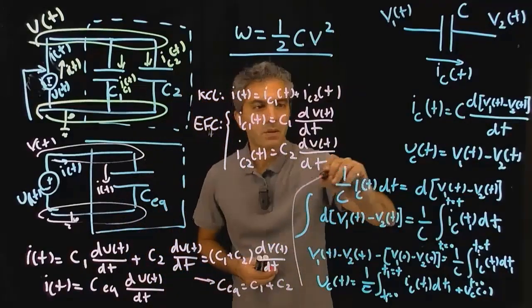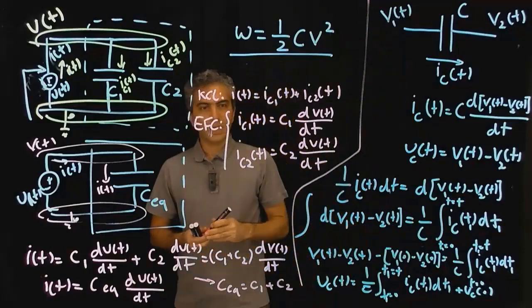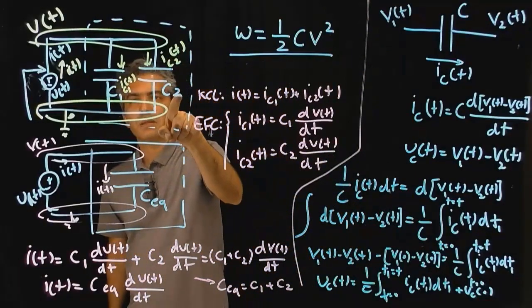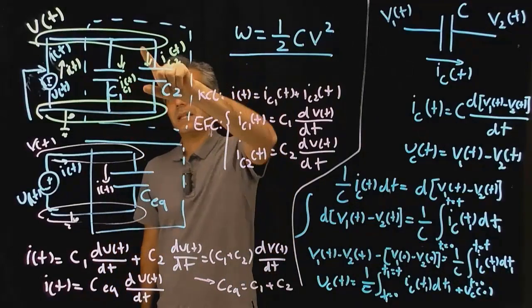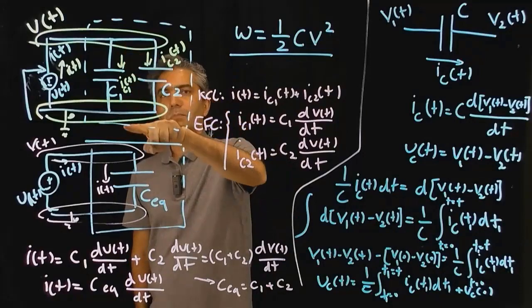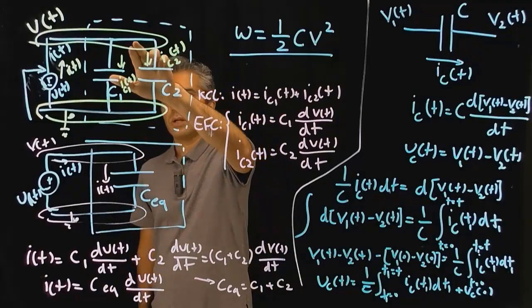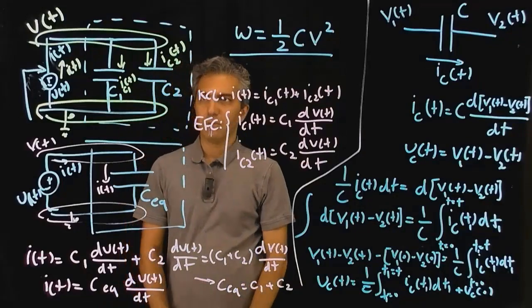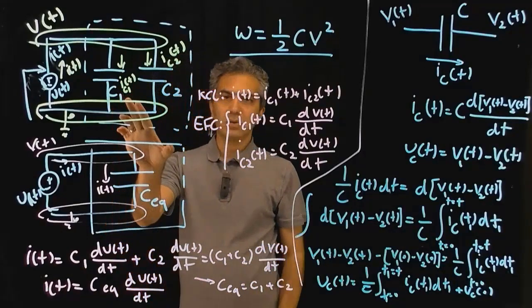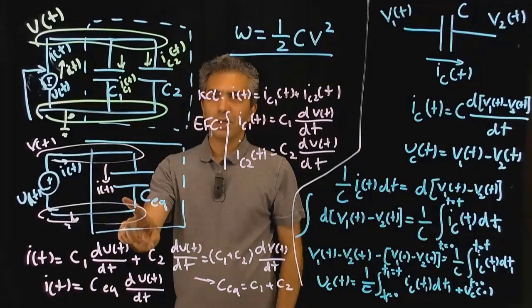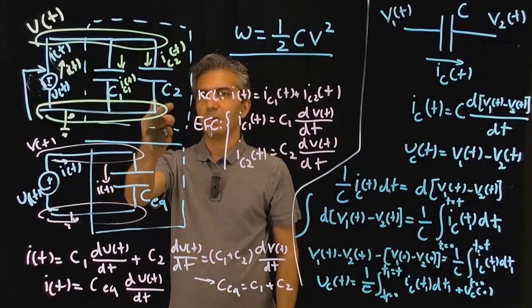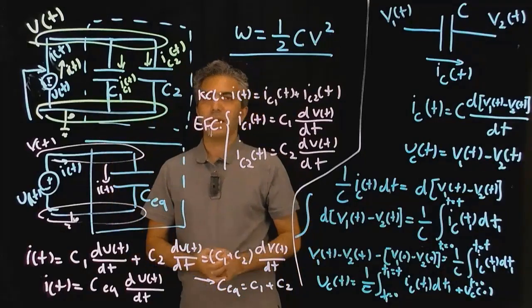Okay? So simply, I proved that if I put these two capacitors in parallel, and what was the meaning of the parallel? That meant that the two components share nodes on both sides. So they share one node on top and share the same node on the bottom. So if they're in parallel to each other, you can take the two, turn them into one equivalent capacitance, and the value for that one equivalent capacitor is basically the value of the capacitance for each one added to each other.